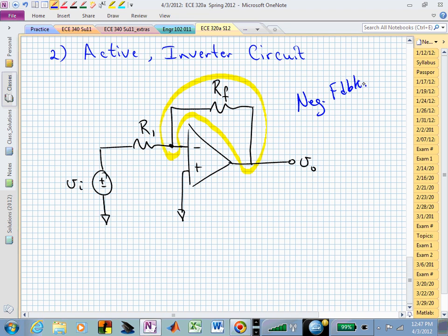So this particular op amp is functioning in a negative feedback configuration, and that allows us now to make these assumptions that you do not have any currents going into the input terminals, and the inverting and non-inverting terminals are at the same potential, the summing point constraint. So you can say effectively that V sub P and V sub N, which I will label as the non-inverting and inverting input pins, are at the same potential.